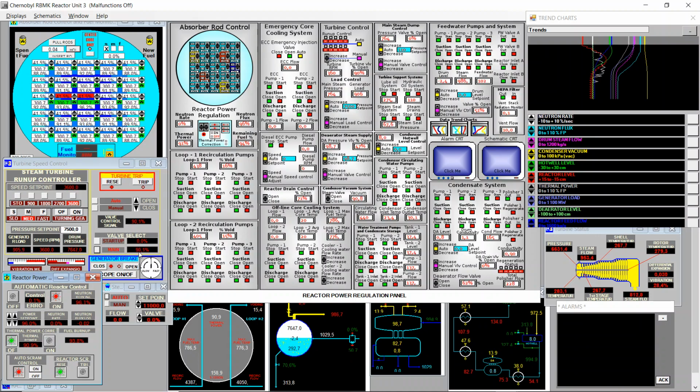The main valve is open at 90%, and this is still automatically governed. Now I will try to adjust a bit more the power set point to the actual minimum, so we can have a bit more power, which is 7355. And we see immediately the power set point increasing, the generated load to 920 megawatts. I will keep increasing the power set point of the reactor to get close to 100%. We cannot reach 100% because if the neutron flux reaches 100%, we have a meltdown.